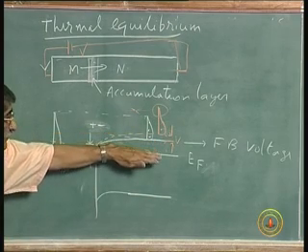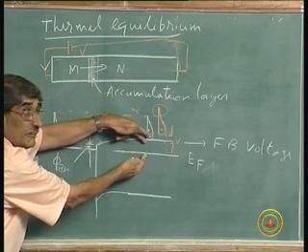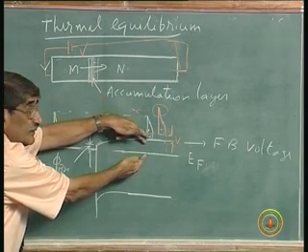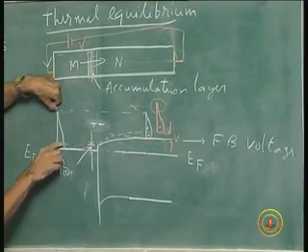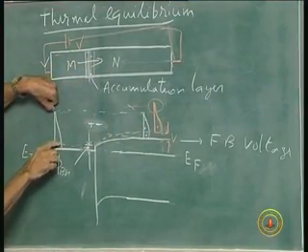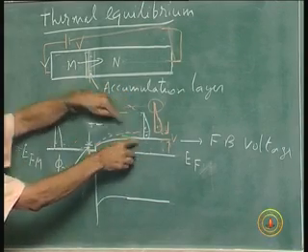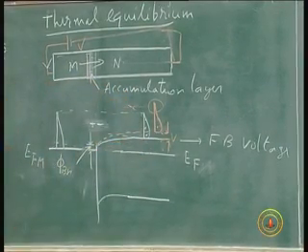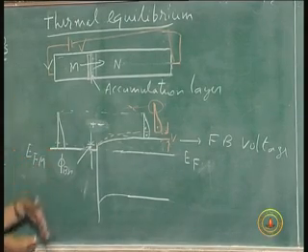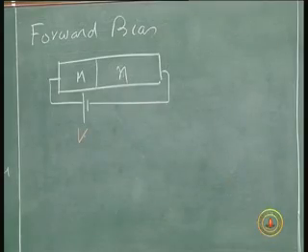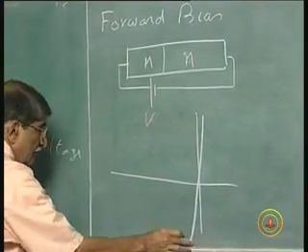This level will come down, that means this whole thing will come down depending upon how much reverse bias. The moment this level comes down, originally only this much were there, that was compensated by that. When this comes down, the number compensating disappears slowly. So, a huge number of electrons can flow. That is why this I naught is large, and you get the IV characteristic like that going down.